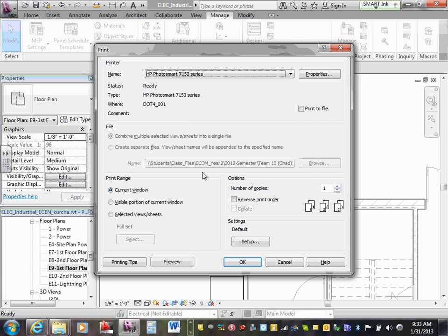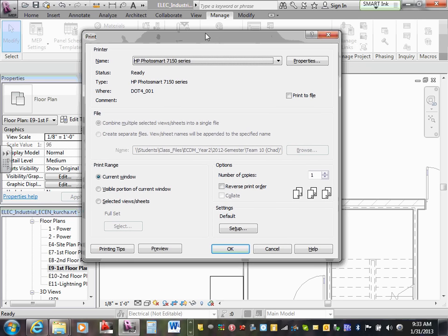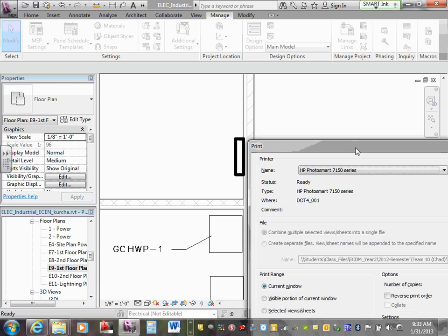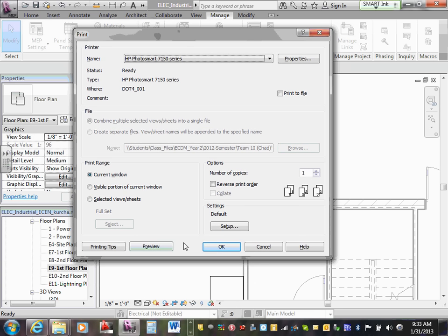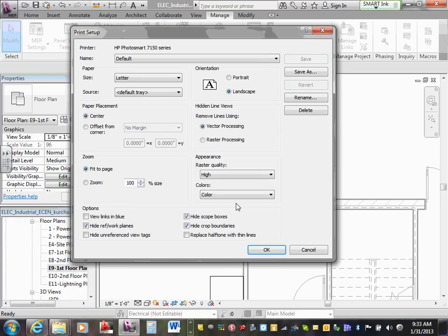The other thing, maybe you guys knew this already, is that when you print, if you wanted that to stay green but plot black, you go to print, under setup, right here, colors. You can print color if you have a color printer, grayscale, or black lines. It looks like it was set to color, so it's going to print color. And if you don't have a color printer, then it'll just shade it, so if it sees a green, it's going to be less than black.